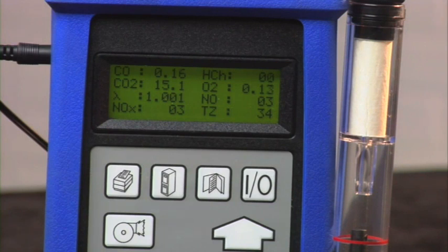We can see this vehicle now, after running for a short period of time and it's warmed up, that lambda is within its limits. Lambda is within 1.000 or very close to that during these conditions. This vehicle is in very good fuel control.